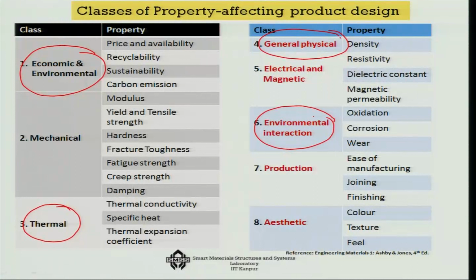So, you need to give even protections from corrosions for them. Oxidations and corrosions are very important factors in terms of those mechanical systems which are generally subjected to the possibilities of environmental vagaries or the possibilities of harmful chemicals, conducting, say for example, gas pipelines. Okay. So, there the chances of corrosion are very high. So, you need to choose a material which will not be getting corroded so fast, in that way reducing the life of the pipeline.